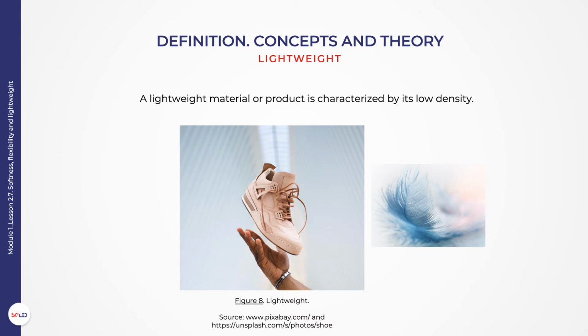Real density is determined by calculating the mass of a material by the volume, excluding the voids. Apparent density is determined by calculating the mass of a material by its volume including the voids. Both the real and apparent densities are important material properties related to a lightweight product. The real density is related with the intrinsic property of the material A, whereas the apparent density is related with the density of the 3D structure made of the material A.